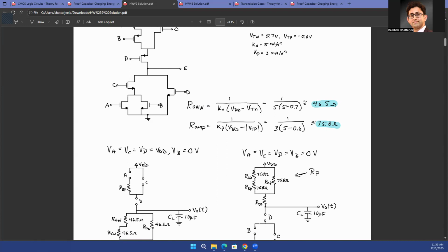That's why people do a divide and conquer approach, dividing it into smaller chunks, even though in the end that might cause more power consumption. At least you can get a higher frequency, because it's easier to control a smaller set of transistors than hundreds of transistors at the same time.